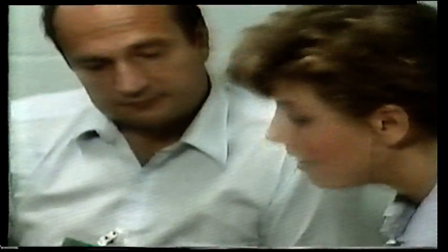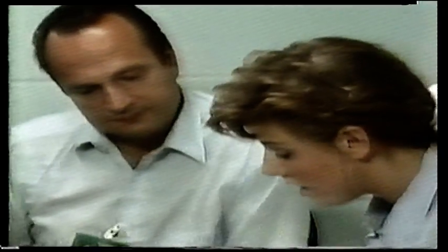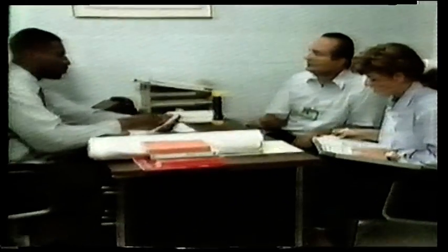Following completion of the survey, the team should return to the facility representative and present a summary of the survey. This provides immediate results and discussion of the facility's needs for cross-connection control. If any existing protection was found, it should be noted. Acknowledgement of existing correct installations may serve as positive reinforcement and encourage an atmosphere more receptive to recommendations concerning additional protection. Following the meeting, the survey team will translate field notes into a formal written presentation combined with appropriate sketches.